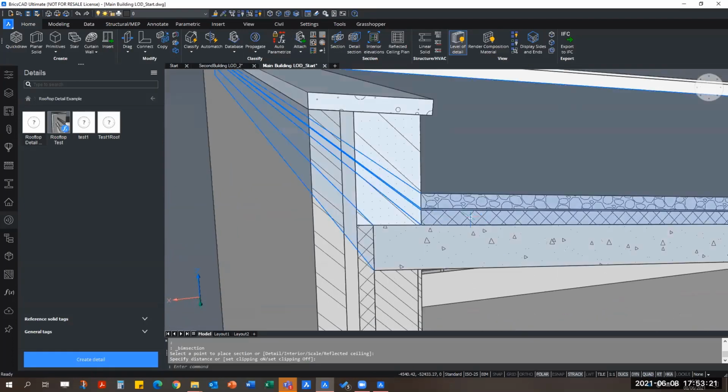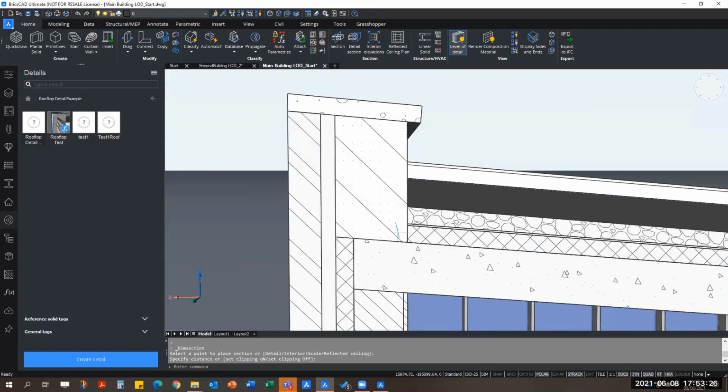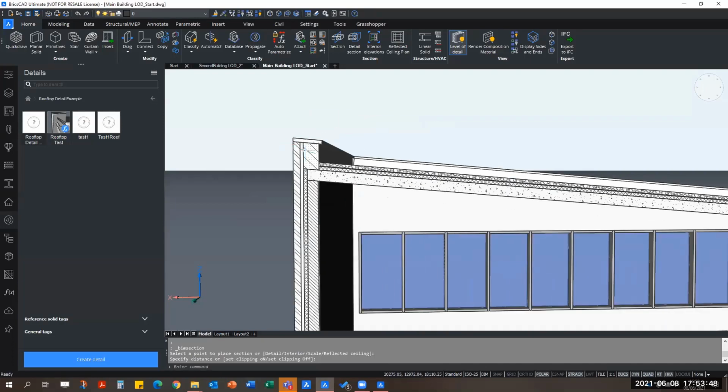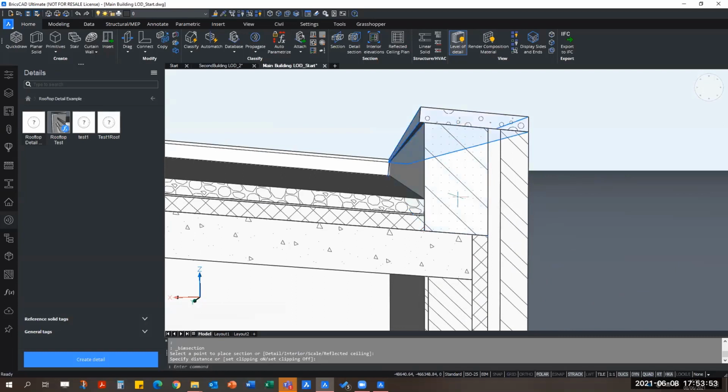And yes, let us draw a section report. And you can see, even at an angle, it's working fine. These lines are parallel because we specified a distance of 355, you remember. These lines are parallel as well because we specified a fixed distance of 50. And these two planes are coinciding. They're basically sitting one on top of another. And that's really important because that's what I want. And in this case, same thing.